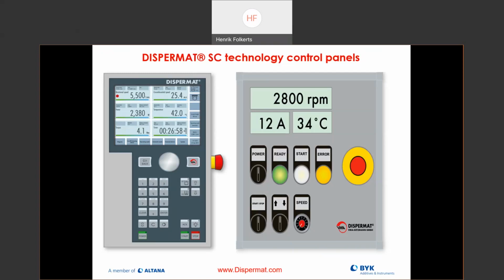So what's really nice about that is now, if I know exactly when I'm running with constant power and I want to upscale, and I know I can process this material in, let's say, 1 hour with 1,000 watts of energy, I can now calculate exactly how much it would cost me to make this material. I can upscale that very easily and also know what the manufacturing costs are to make a particular product because I know how much energy I'm using over a certain time. So that's one of the big advantages of using constant power over just constant speed.